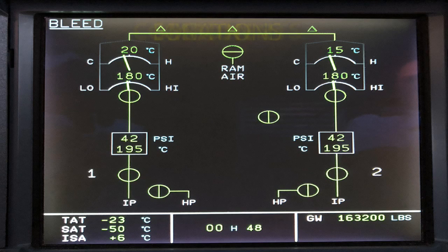The Precooler exchanger, along with the fan air valve, the fan air valve thermostat, and obviously the outlet temperature sensor for the Precooler exchanger, all of that is located, with the exception of the sensor, but the parts I just mentioned, the fan air valve and thermostat, are located in the engine pylon. That's where you'll find the bleed air Precooler exchanger as well. So all that's in the engine pylon. And the Precooler exchanger outlet temperature sensor, there's a sensor in the wing leading edge that's aft of that engine pylon. So you'll find that there.